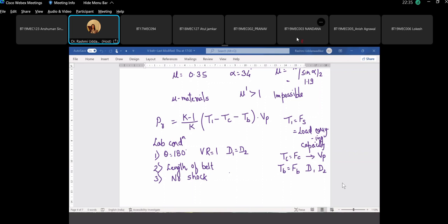What is the next table indicating? Nominal inside length and the pitch. From the formula for length of the belt, the length that we are getting is the pitch length, the nominal pitch length. And the belt is designated using the inside length. Now, when we calculate the length of the belt, that will not be a standard length, right? You will get different values for different diameters.